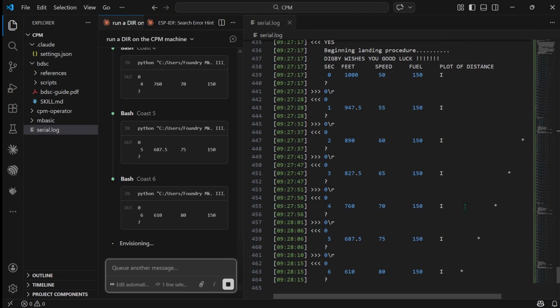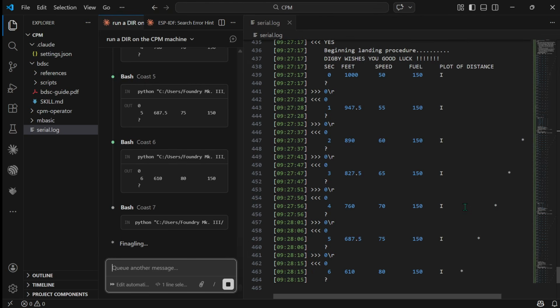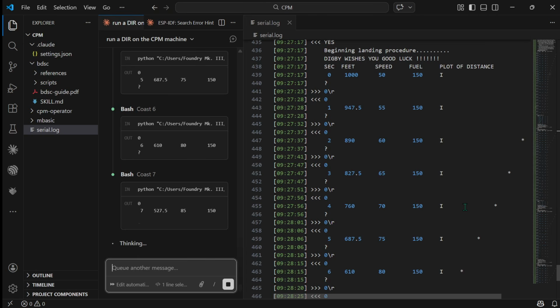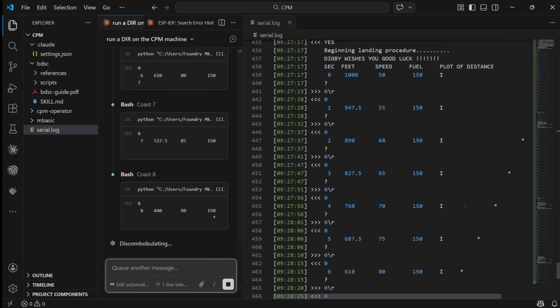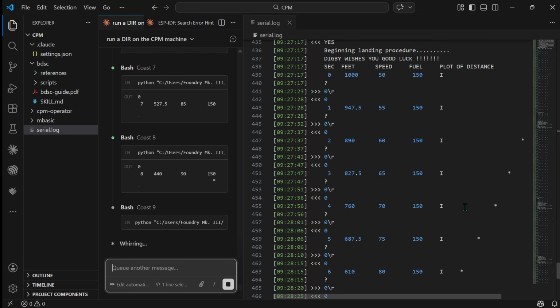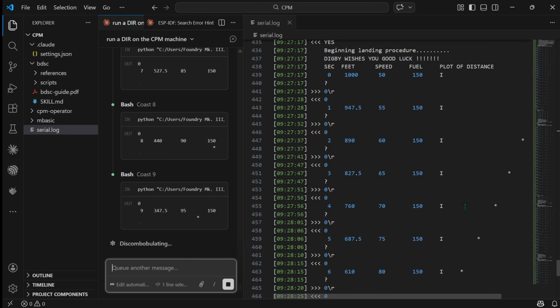It got the binary to voltage conversion done. It runs from like minus 2.56 to plus 2.54 volts, I think. It's a bipolar A to D, and it got all the scaling correct, I guess is what I'm trying to say here. First time, I was really amazed. It made a mistake up front about what ports the card was on, and it corrected those by feedback from one of the agents as it analyzed online documentation. I pointed it at local documentation as well.